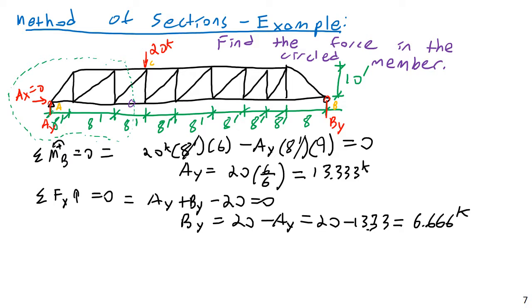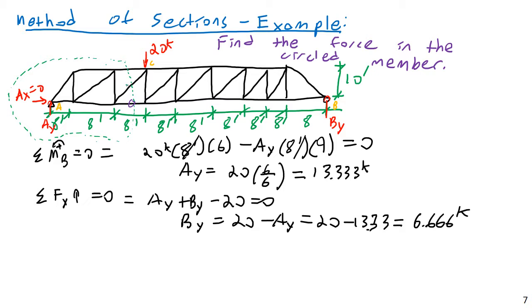So the reaction force, you might wonder, how does that force have an effect? Well, it's already baked into our AY. So let's look at a free body diagram of just this section here. I'm going to replace this entire section with just a block to show that I'm treating it as a single rigid body, and then I'm going to replace any of the cut members with just a simple line force.